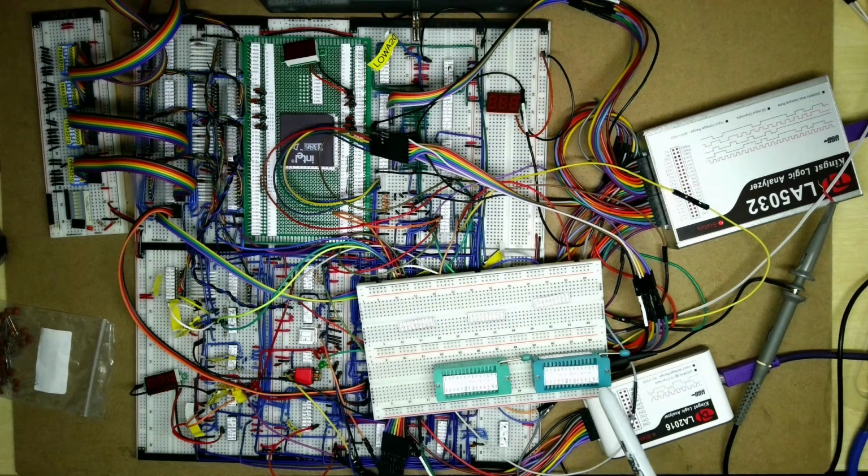Now, during this video, what we're going to do is add two 32K EEPROMs. These EEPROMs are electrically erasable, programmable, read-only memories. These will be having the system BIOS in future videos, but to start with, I'm just going to put some simple test software in here because at the moment we don't have any RAM. That's going to come in a couple of videos' time.